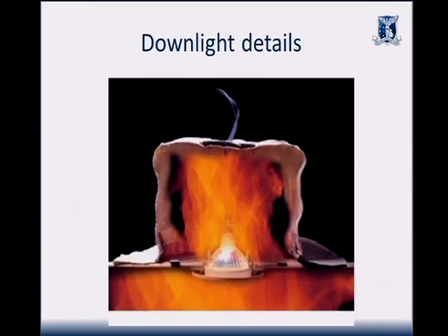The other big one is that well-sealed buildings, which is something that's very popular now, are a problem because of mould, and they're bad for your health, and they grow all that nasty stuff. So we've got to try and see where there's a problem, chase back through the chain. What's actually causing that house to have a mould problem is a lack of ventilation.